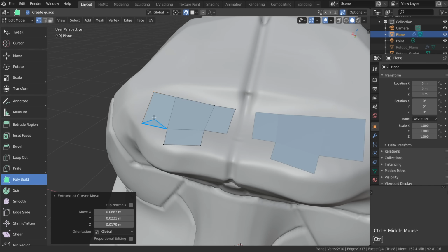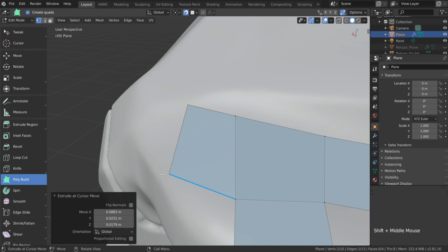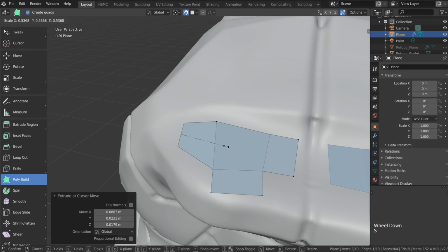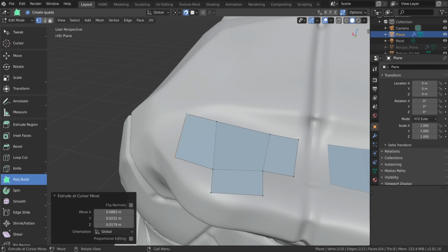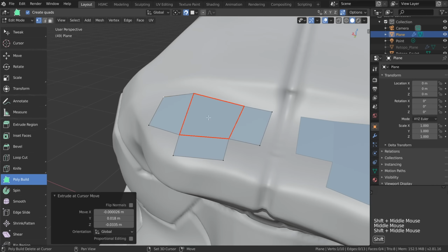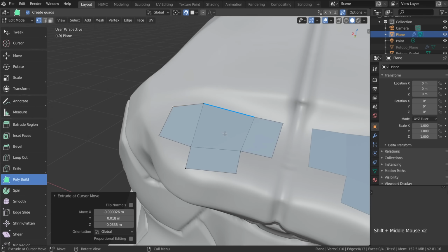What you might be able to see is that the two vertices there are selected, so that allows us to hit S for scaling or R to rotate, and if we want to reposition them slightly, we can left click and drag over the vertex there once it turns blue. Now whilst navigating around, you might have seen the red flashes there.